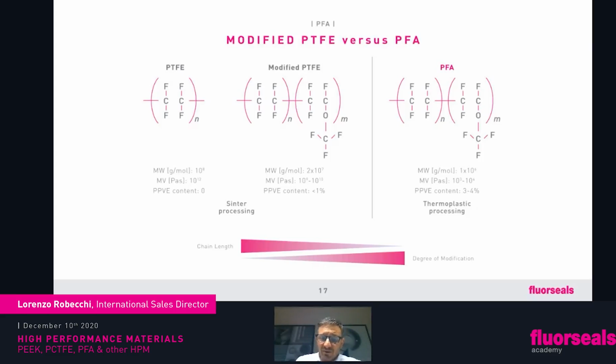And so the other way around, whoever was doing the other plastic was not really doing PTFE. Why is that? Because you need a different technology, because the chain of the material is different. And this difference in chain length means you need to change your technology, okay? And this is interesting. On one side, PTFE, in the middle, kind of in between, modified PTFE, but yet it is still on the side of PTFE. You still need the technology that you need for PTFE.